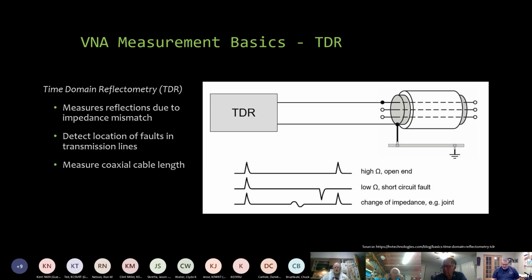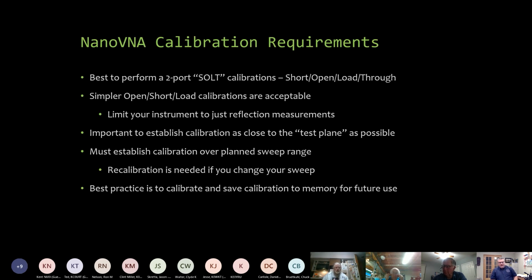So the next step really to getting started with our Nano VNA is to start with calibration. And the best method for this, and we'll go through it here in just a minute, again with our live demo, is to perform a two-port calibration.